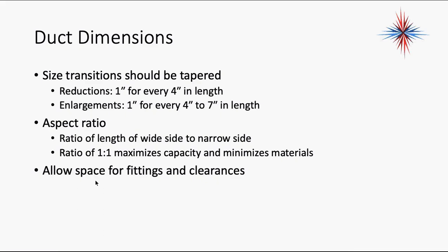Okay, so reading blueprints becomes very, very important in new construction because you have to know what the finished product is going to look like. Because if you have an air handler blocked in a corner of the attic with ductwork and everything else, your service techs are going to hate you. Okay, you have to allow space for service.